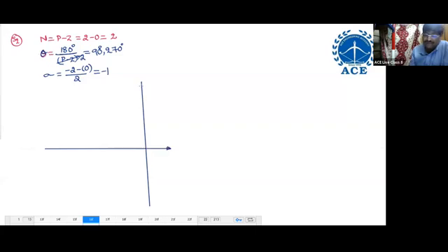One pole at the origin, K equal to 0. One pole at -2, K equal to 0. Here root locus branches exist. The breakpoint is -1 and the centroid is also -1.